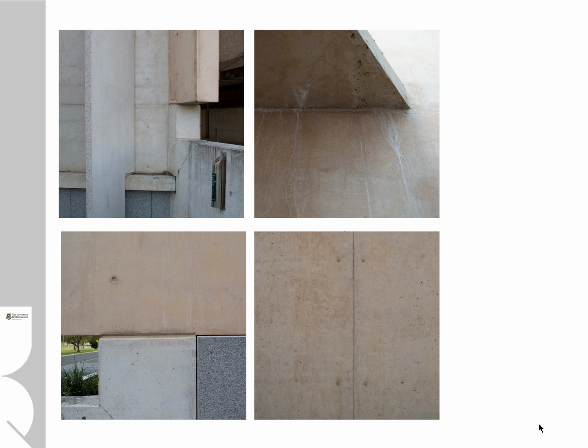Now, we can see there's been in this instance a very close attention to detail that hasn't quite come off in some instances. In the bottom you can see a very lovely set of details where we've got a coloured concrete in situ on top of a grey coloured concrete with a stone cladding insert, and all three of these elements are coming together rather nicely. You can see that there's been a construction joint built into the formwork to transition between one type of concrete to the next.